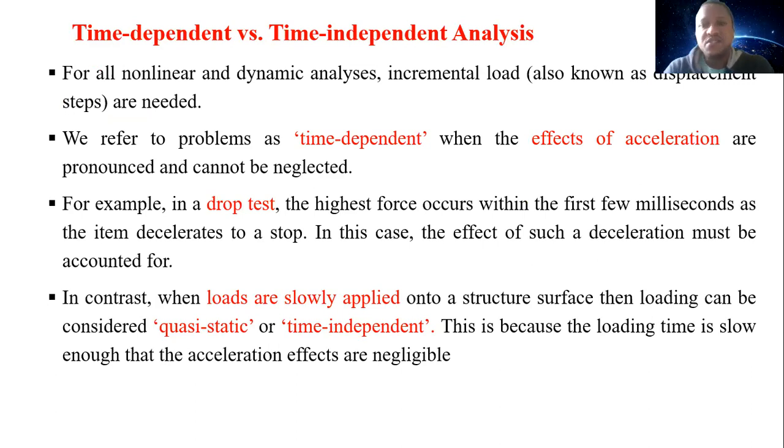Time-dependent versus time-independent analysis. For all nonlinear and dynamic analysis, incremental loads are needed, which are also known as displacement steps. We refer to the problem as time-dependent when the effect of accelerations is pronounced and cannot be neglected. For example, in a drop test, the highest force occurs within the first few milliseconds as the item decelerates to stop.